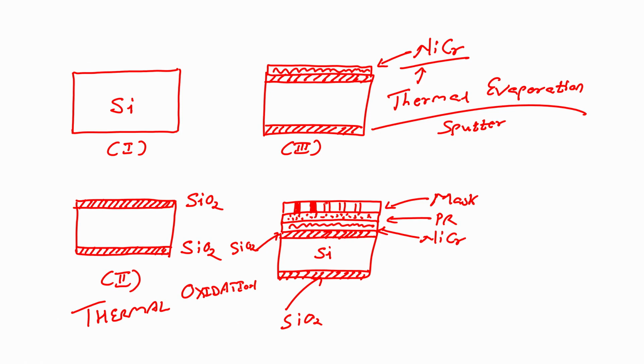You have seen in the lithography section what the importance of bright field and dark field is. So, this is my bright field mask, and this photoresist is positive photoresist. Next step is, I will expose this wafer with UV light. That is why it is called UV lithography.